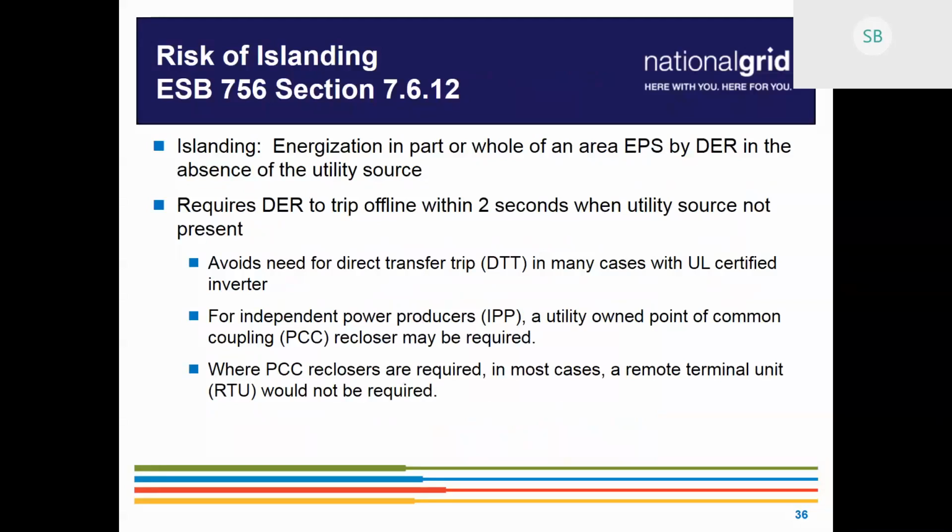Instead of that, for at least the independent power producers, maybe not so much the behind-the-meter customers, we are requiring a recloser at the head of the site at the PCC. So you may have had a site that doesn't require a recloser because of its size, but because of islanding concerns, we might require one. And in the past, we have required remote terminal units for monitoring and control of the site. But with the recloser there now, in many cases, we can avoid that.